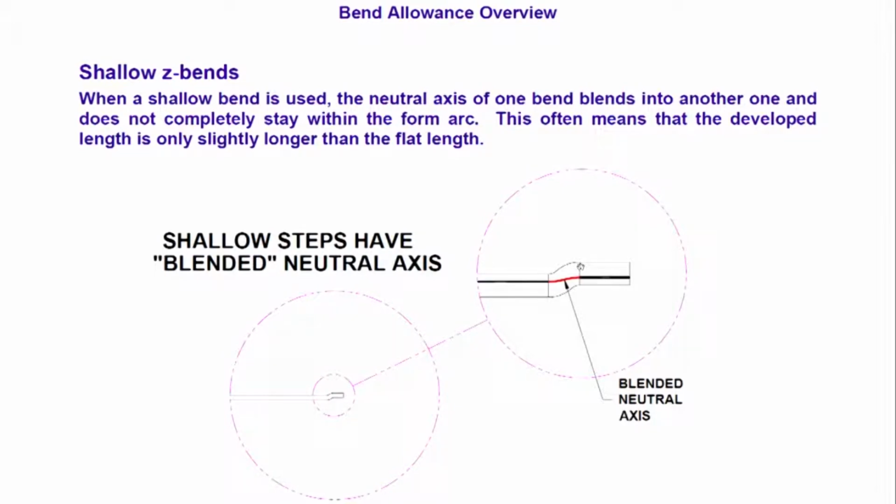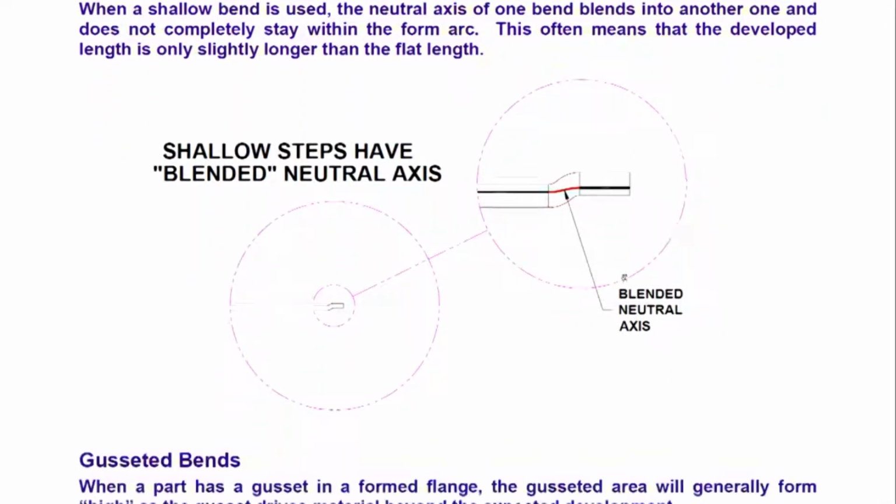Suppose there is only one thickness offset. In this case the neutral axis is likely to not have too much of an additional effect. So here length is only slightly longer. When they talk about slightly longer, it is probably not even measurable. It should be the order of 0.05 or 0.1 millimeter long, and then it does not matter because the limbs themselves, or the order of limbs, are so small.